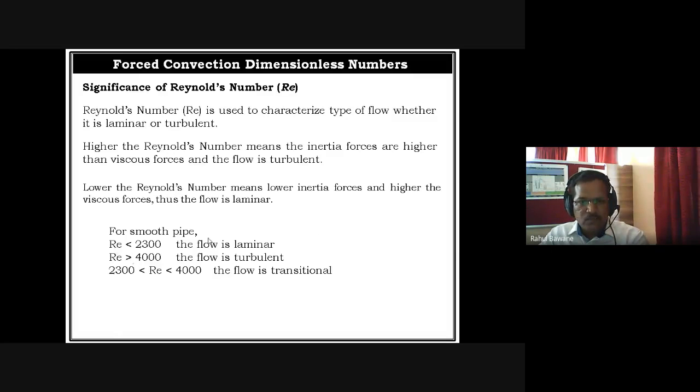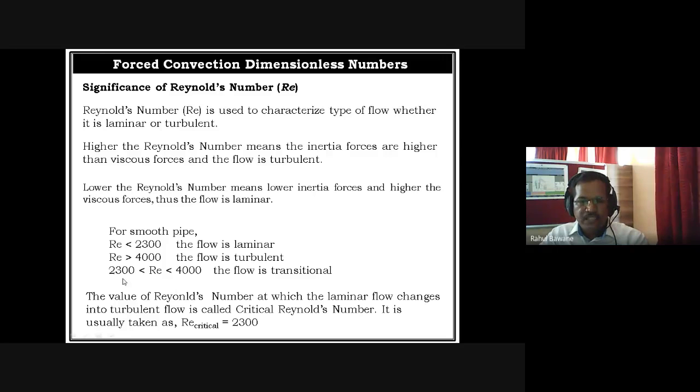For categorization, if Reynolds number is lesser than 2300, the flow is definitely laminar. Greater than 4000, it is turbulent, and in between 2300 and 4000 it is transitional flow. This is generalized, and we know all this, but remember, whenever there is a numerical and they provide data for laminar flow, such as Re is 5000, then we have to consider Reynolds number lesser than 5000 as laminar, because it is given for that particular numerical.